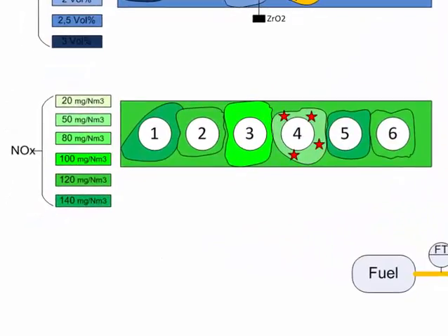The main nitrogen oxide formation mechanism in fuel gases without fuel-bound nitrogen is the so-called thermal NOx mechanism. This means the higher the temperature peak inside a flame, the more nitrogen oxide is produced. Besides temperature, the partial pressure of oxygen also influences nitrogen oxide formation. Most often, the more excess air a burner operates at, the more nitrogen oxide it produces, at least in the range between 1 and 5 or 6 volume% of oxygen. Above this oxygen content, the flame cooling effects may reduce nitrogen oxide again.